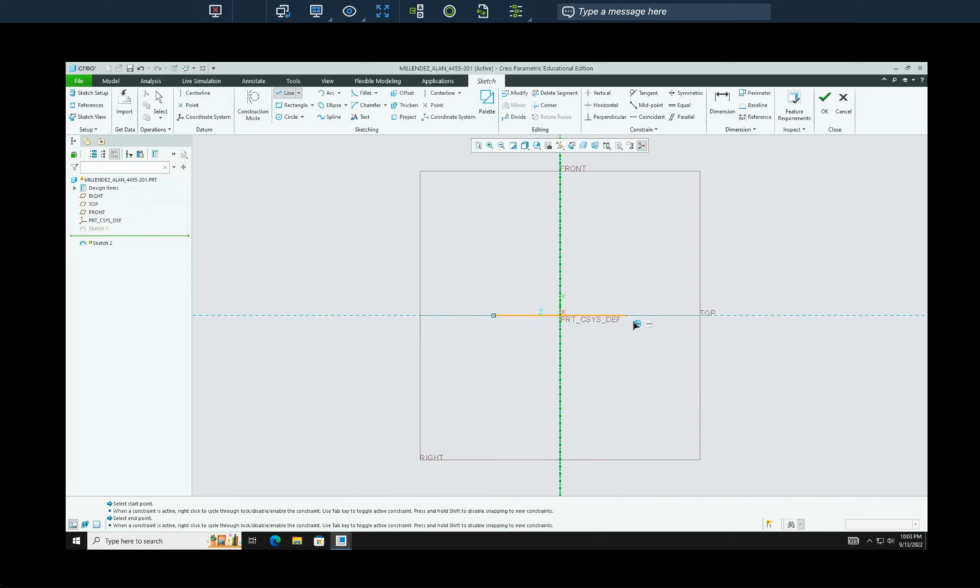Because you pass through a center line, it will assume that you created the center line to mark the center of any object that you're going to start from the left all the way to the right. So can't go further because you have a center line. So click there, and then press the middle button or the scroll wheel to stop, and there's your first line, and the middle of this line is the center of this green line here that I'm highlighting.